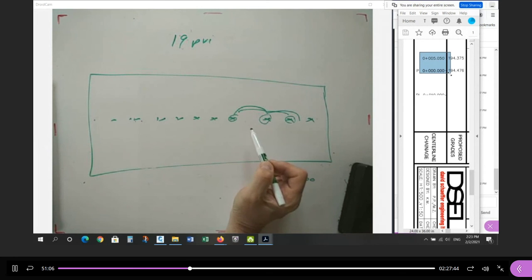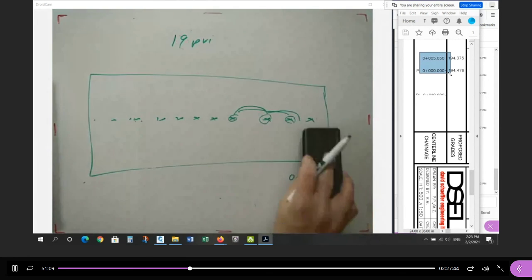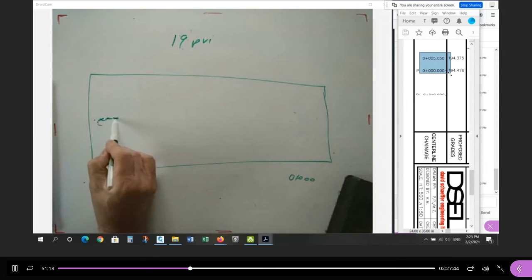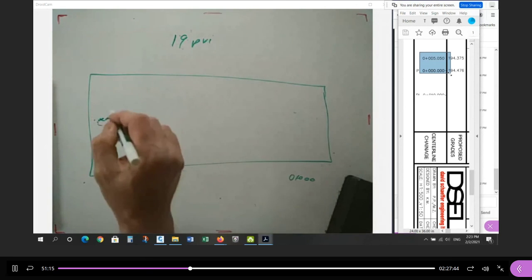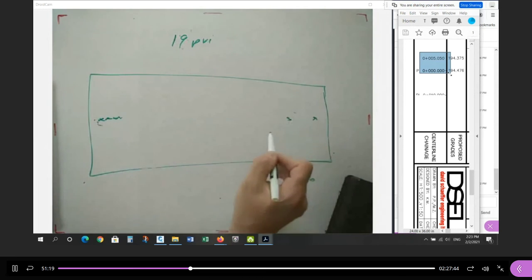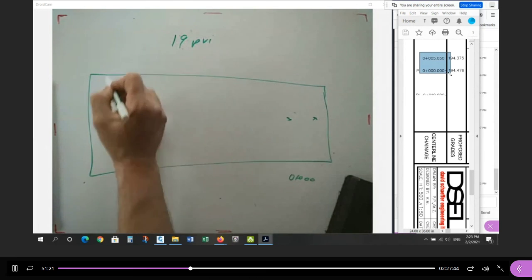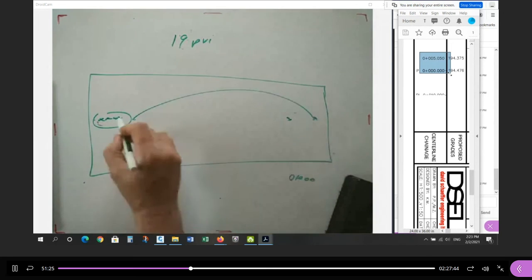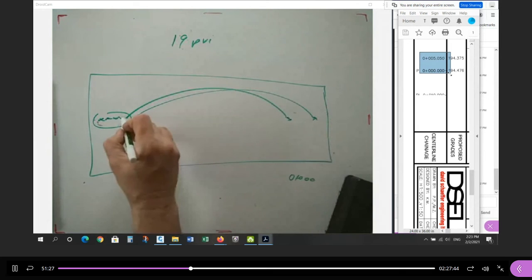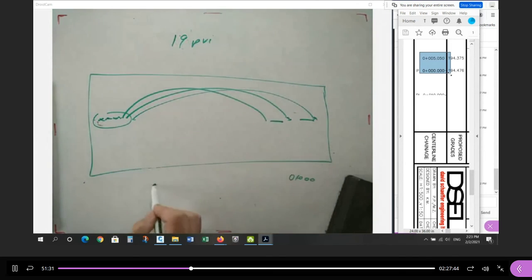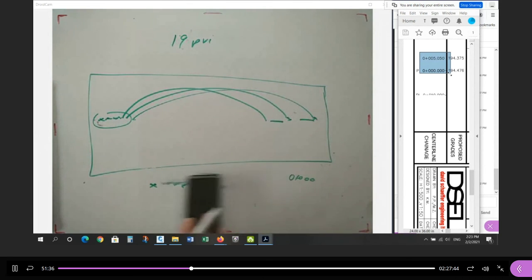Okay? And it's a source of frustration. So don't try and guess where they should be. Put them all past the last one. Put them all near the end. And as you change the station values, they will then be put into their proper location. So what we're doing is going from points here, taking the first one and pushing it back, taking the next one and pushing it back, taking the third one and pushing it back, and then we're creating the gap. So I'm working between points all the time instead of trying to guess.